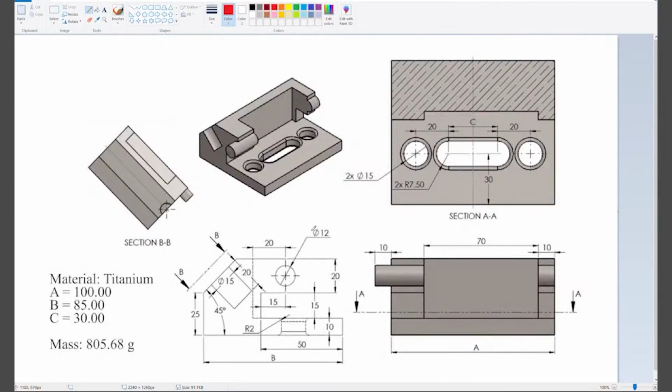Next, we're going to look at some of the features that you're going to have to know how to do. This is a fillet here, right? And we can find the dimension of this fillet: here's the R again, radius of 2. Fortunately for fillets, you're already inputting the radius, so this is not trying to trick you at all. This radius is 2, and it goes all the way along this edge, so we know that the top and bottom of these holes are filleted.